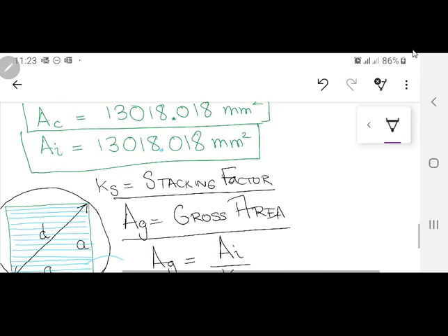And what is the stacking factor range? This stacking factor range is from 0.85 to 0.95. I hope you are getting the idea. What does stacking factor mean? If your laborer or your workmanship is good, your stacking factor will be something like 0.95. आपका resin भी अच्छा है, पतला है, it's a good insulator also, not that very weak one. So you are going to have 0.95.